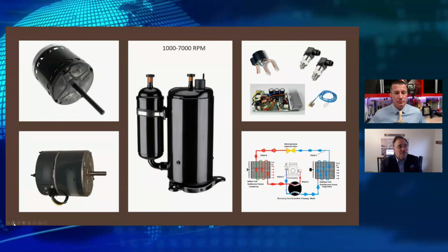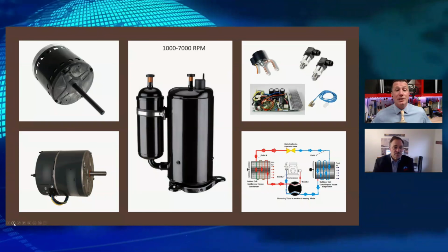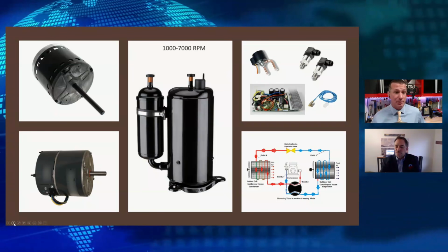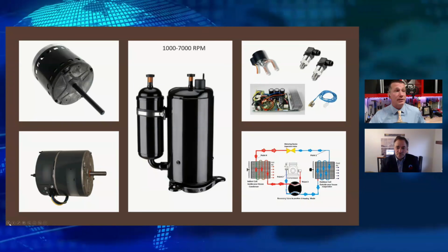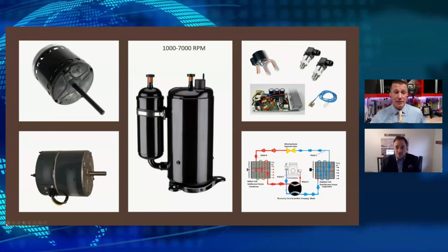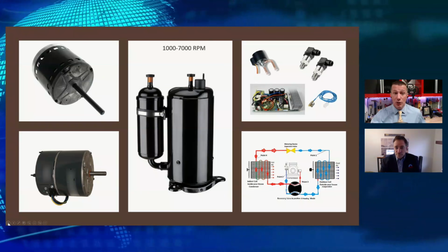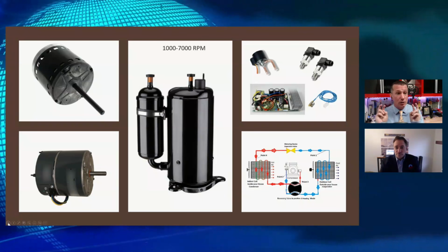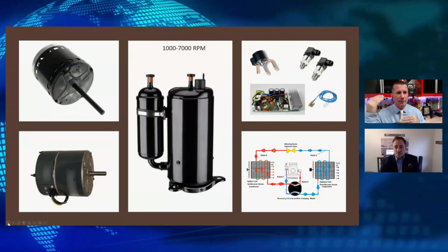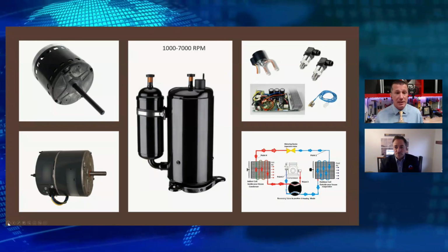Do all inverter heat pumps use electronic expansion valves? No, they don't. So it kind of comes back into the same philosophy. Electronic expansion valves are the highest performing. Absolutely. Are they required to hit some of those higher SEER units? No, they're not. So we have a lot of equipment out there that will operate in fairly low ambient conditions on a good, what we typically call inverter-tuned thermostatic expansion valve, which means it has the capability of opening and closing in a pretty significant range, more than we would have with a single or 2-stage compressor.